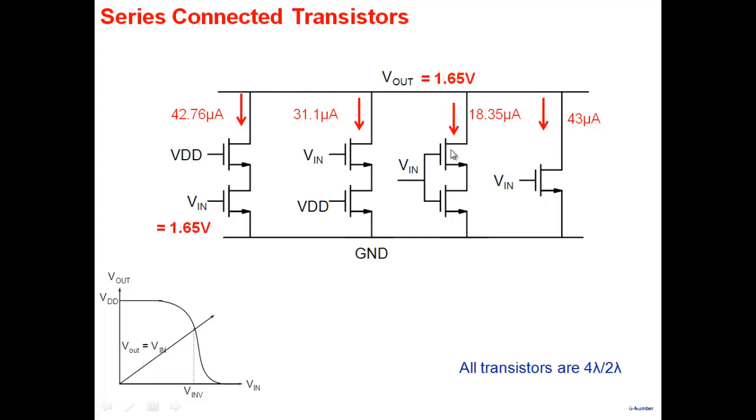we can then show that when you take two NMOSes and you connect them like this here, it can be thought of as a single NMOS, but with half the size. Through equations, one can show that. Two NMOSes connected in series with both their gates tied together and with identical threshold voltage, effectively behaves like a single NMOS with half the size as this one, which is sort of what you are seeing here. This is 4 lambda by 2 lambda, and we are saying this behaves as if it's a single transistor with half the size. So it behaves like a 2 lambda by 2 lambda.